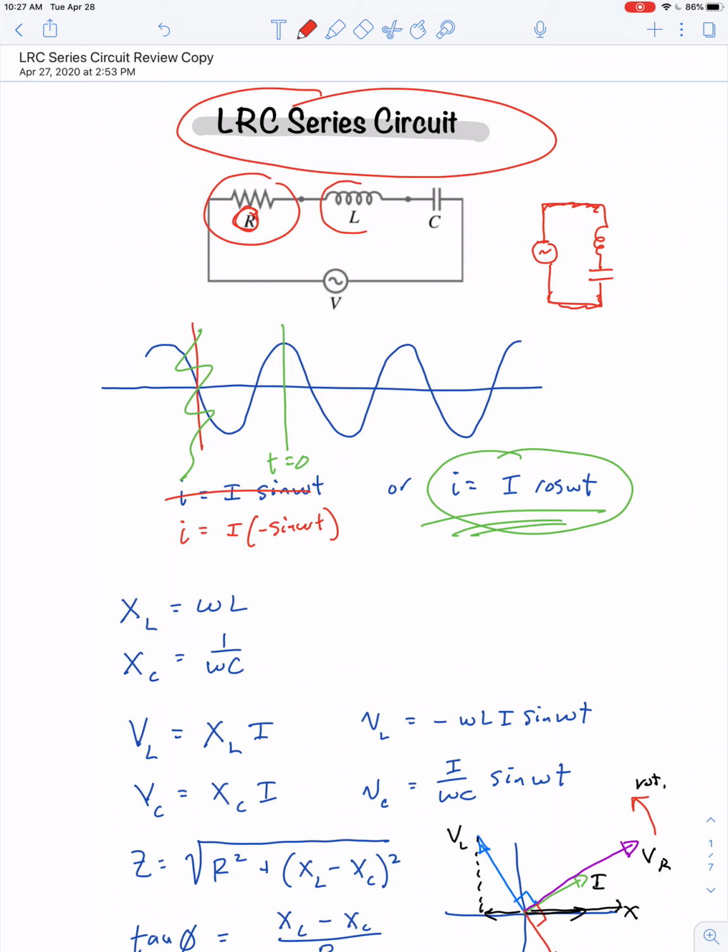Can the same thing be said about inductance? Yeah, absolutely. You say, I'm going to try to make a circuit that only has resistance and capacitance. Well, you can't make a complete circuit without at least having one loop. And when current flows through a loop, it behaves like an electromagnet. But it imposes flux onto itself, and so there is a form of inductance just by virtue of having at least one loop, and every circuit is always at least one loop. So there's always some non-zero, albeit might be very small, amount of inductance.